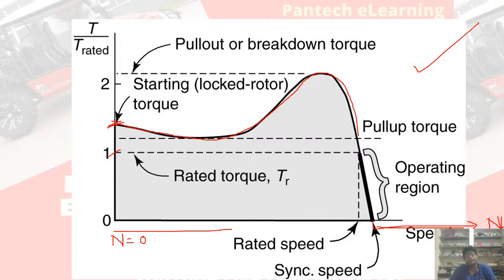So these things are continuously happening inside the machine. Due to this reason, this asynchronous induction machine is never able to reach or catch the synchronous speed. And due to this reason, till it is getting accelerated, it is drawing very high current.